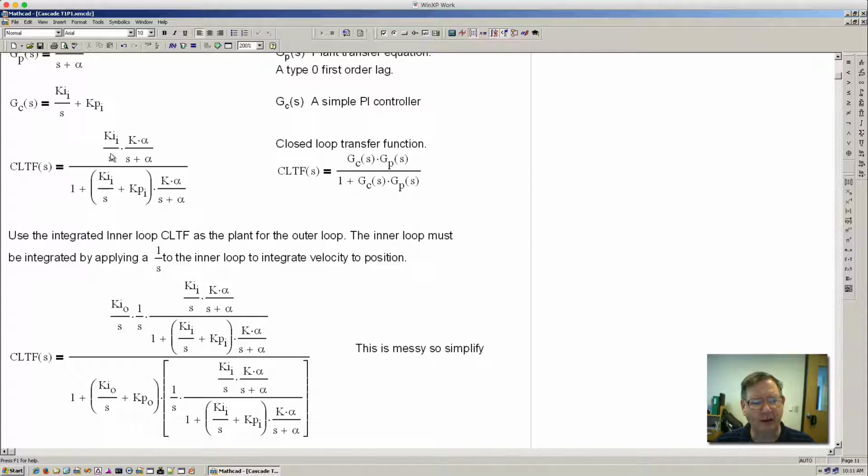And when I do this, it means that the integrator and the proportional term are using the feedback, but in the forward direction, this is using the error up here. So the errors get used on these terms here that are both here and here. And then this is using changes in the actual position for the proportional gain. And what that does is it reduces the bandwidth.